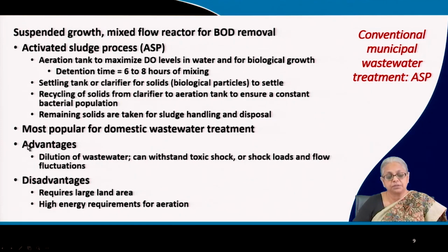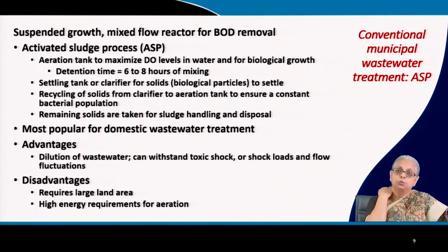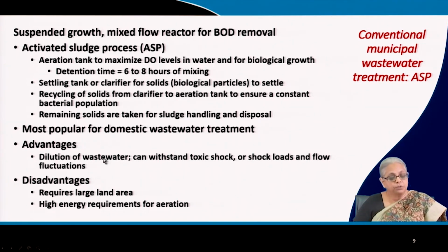But because there is dilution of wastewater in this process, the process itself is slightly less vulnerable to all these variations in comparison to processes like trickling filters and rotating biological contactors. Then we come to what are the problems. The first problem is the large land area.